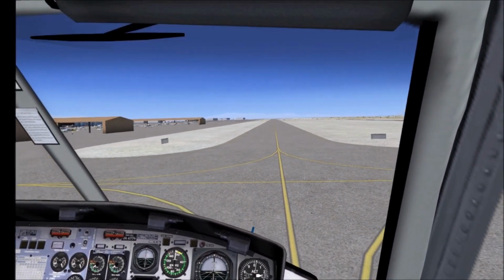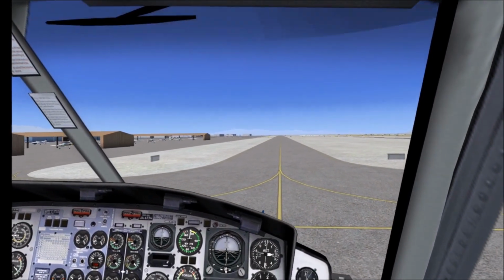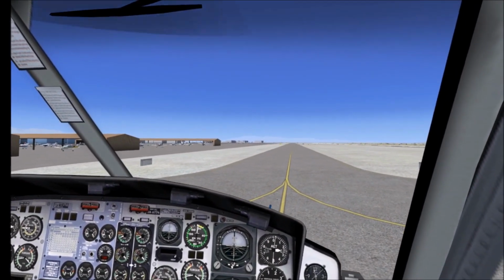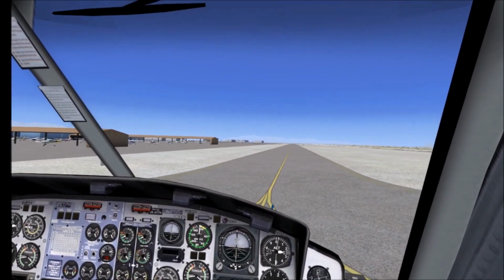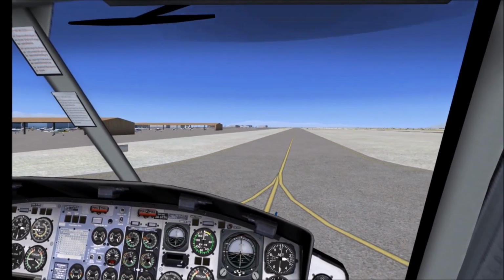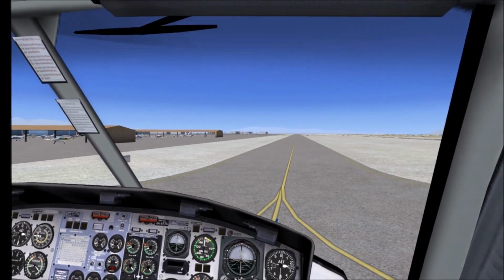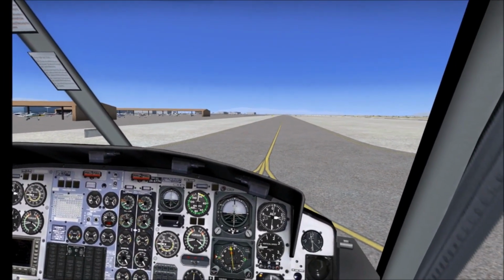Let's try that one more time, because we just sort of accelerated really smoothly through. So what I would expect to see is just a little bit of a dip as we get through transverse flow, and then a nice efficiency increase in the rotor and get us a positive rate of climb.